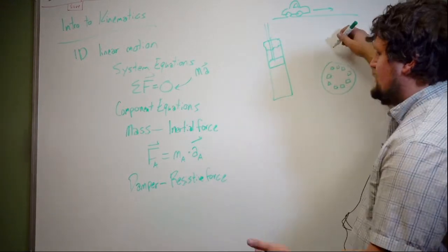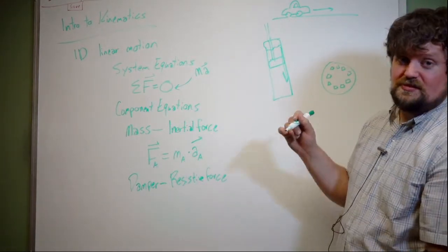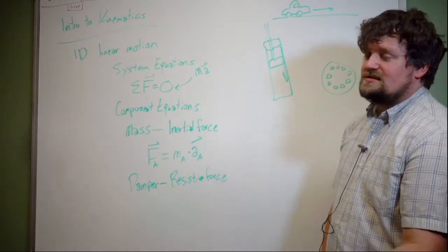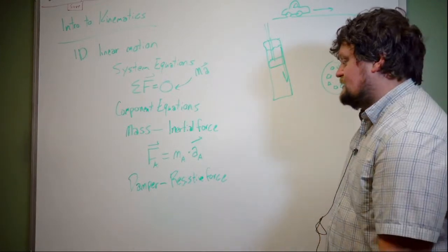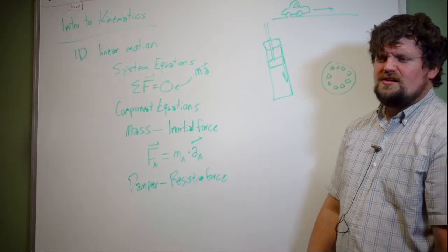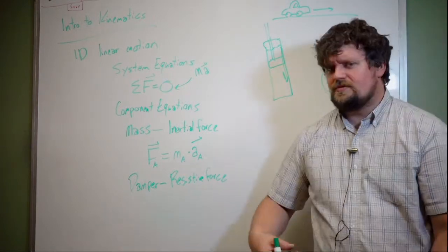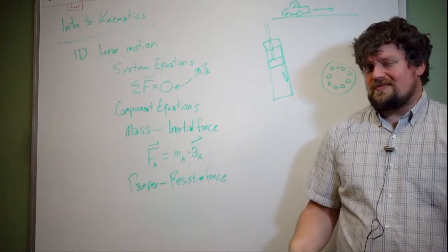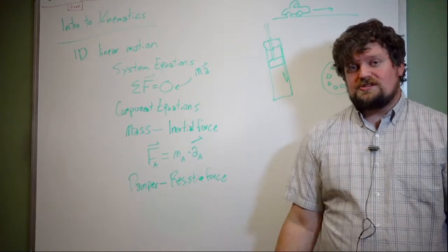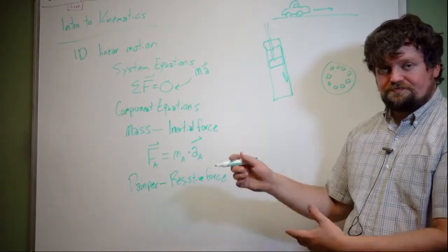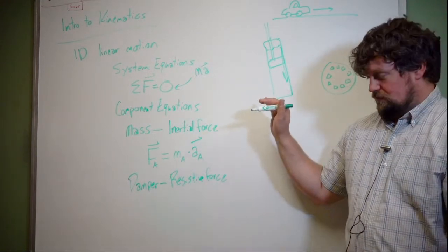As this potato masher object, this damper, travels through the tube, you experience a lot of fluid resistance to motion. That's what a damper does: there's a fluid resistance to movement. That does incur a kind of force, similar to what we would consider friction. In mechanical engineering, there's also bearing resistance. Bearings are often lubricated, so while it's modeled like this, bearing resistance can be considered this way too. We'll get into that later. But this is what a damper is. It is friction.